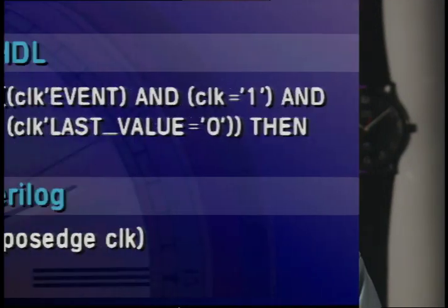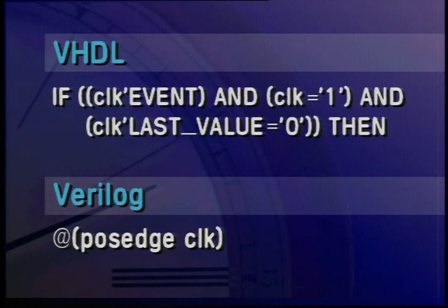Verilog also has reasonable model constraints. The resolution functions which are built in are adequate. There are 8 of them, they are not exotic, and they are generally sufficient. While there may be cases where the user would like to define his own, as he can do in VHDL, that is pretty rare. An example of reasonable model constraints is the use of events on signals.